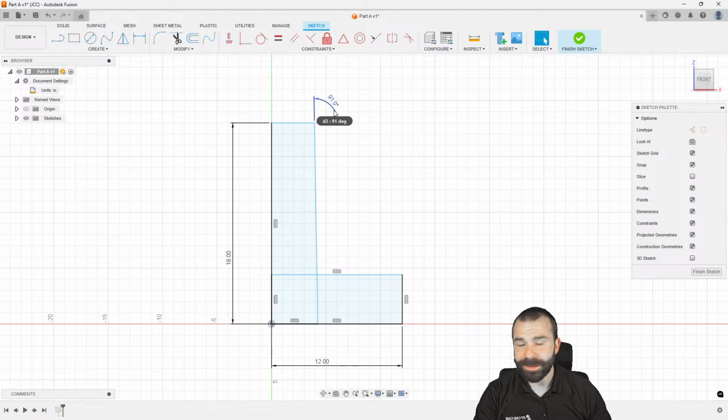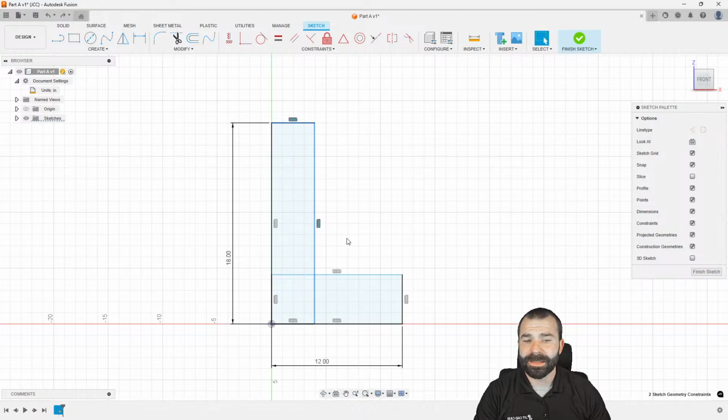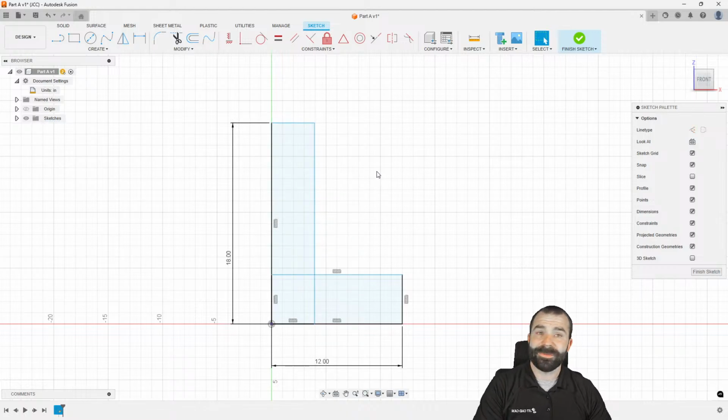So what did oh, great question, Matt. So what I actually did there is I actually just clicked on the constraint itself. So if I go in and I click and then I held control and I clicked the second one, again, it's not necessarily means these two are actually constrained to one another. But as you're seeing, I can highlight those constraints and hit my delete key on my keyboard and get rid of them. If you were to highlight them again and right click, you also have delete in this pinwheel, which is a very handy tool.